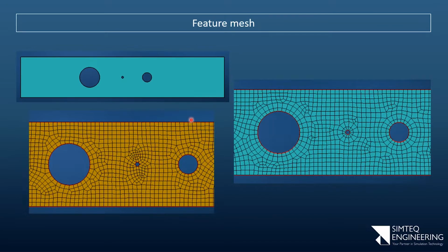If I use a feature type mesh, something like a washer in this case, I can specify these semi-perfect elements surrounding the holes. So in this example, I specified I want 2 elements surrounding it, and I specified the ratio of what those length to the second element's length should be. So you can already see some issues if you're again trying to do everything simultaneously. These elements are squashed a bit in terms of it's short radially and a bit longer in the circumference, while these are the opposite. So ideally, I want to move that row of nodes closer, so that first row of elements is a thinner section.